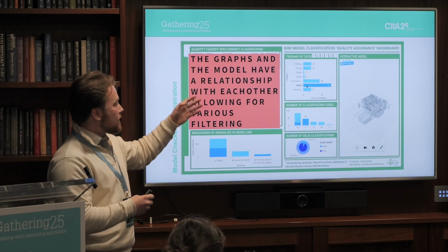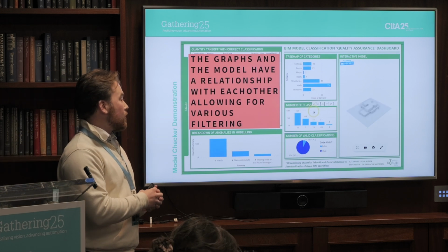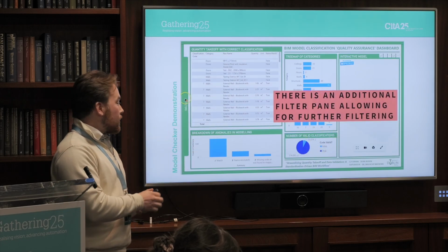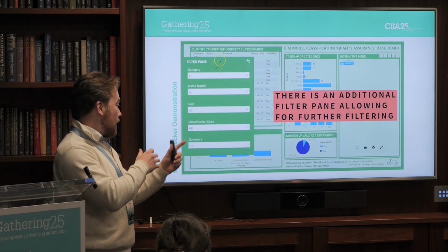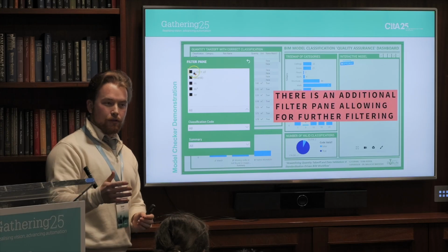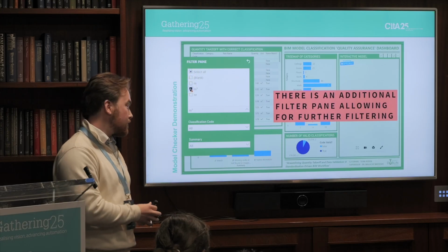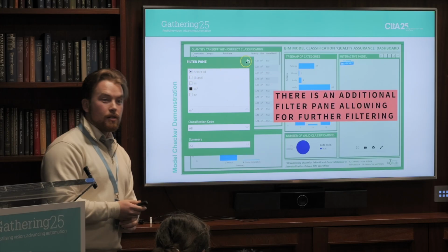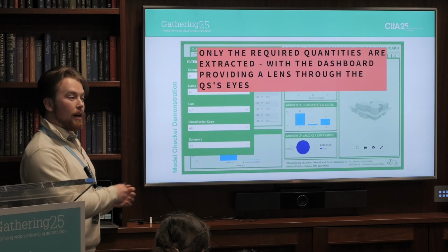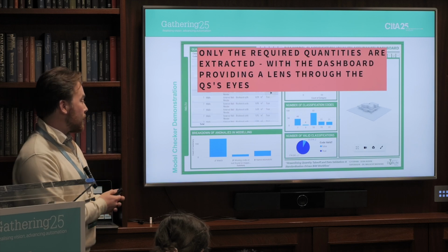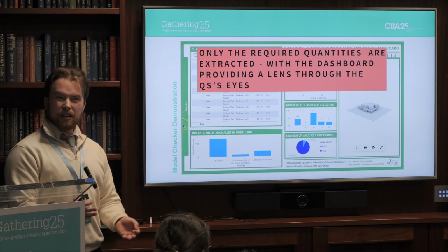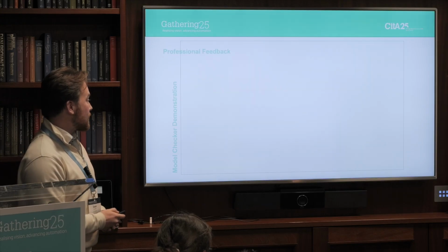It will give a breakdown of all the categories within the model. It'll give a breakdown of what classifications from the ARM5 are being used. It'll also give you a breakdown of how many of the elements in the model are misclassified versus correctly classified. So if we can see that the designer has misclassified 10 of the elements, or 20% of the elements, you can go back and change that. That's the general idea behind this, and it's in a format that's accessible for any stakeholders to assess.